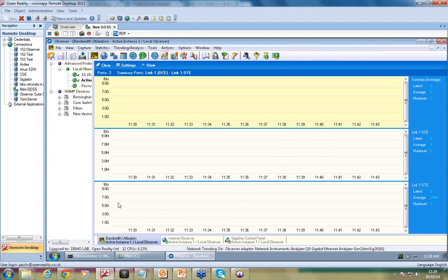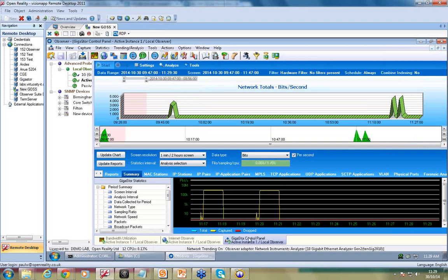So we'll see it in one direction because it's a one-way traffic test on here. You'll see the total at the top, the average of both, and then the direction it's going in. Within the capture screen, this gives you a captured window versus any drops. So hopefully what we're going to see is the ability to capture traffic at 10 gig wire speed without dropping frames, from a portable unit. This particular device has got 4 terabytes of storage on, so it's a first in, first out buffer.